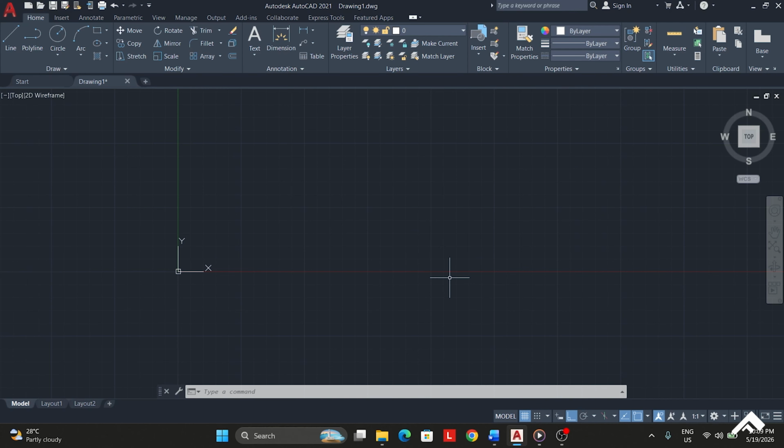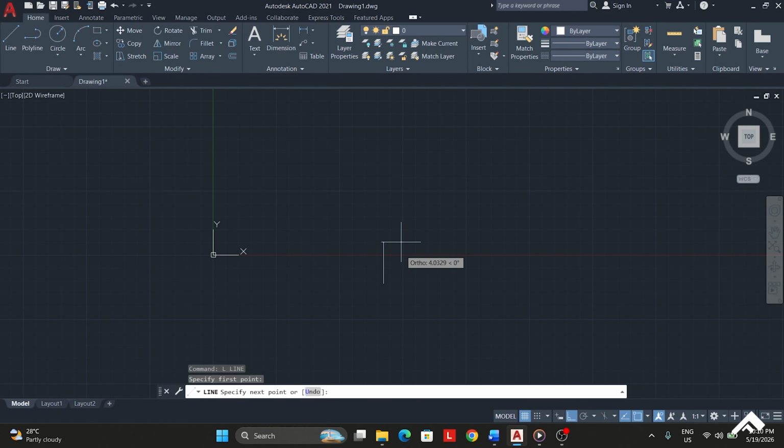Now, let's look at the bottom status bar. These little buttons are extremely important. Some common ones are Grid, Snap, Ortho, Polar Tracking, Object Snap. These settings affect how your cursor behaves while drafting. For example, turning on Ortho mode locks movement horizontally and vertically, like this one. Like that. It is very useful for architectural drafting. We'll use this heavily later.